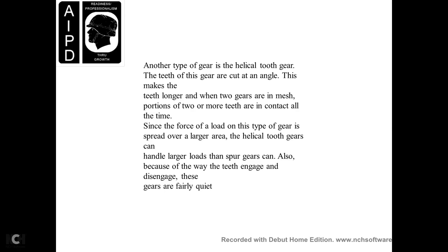The force is shared among the teeth and spread over a larger area. Helical tooth gears can handle larger loads than spur gears, and because of the way the teeth engage and disengage, the gears are fairly quiet.